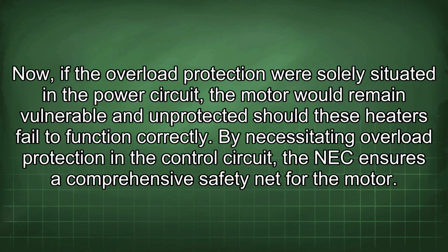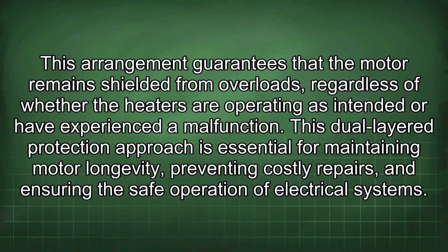Now, if the overload protection were solely situated in the power circuit, the motor would remain vulnerable and unprotected should these heaters fail to function correctly. By necessitating overload protection in the control circuit, the NEC ensures a comprehensive safety net for the motor. This arrangement guarantees that the motor remains shielded from overloads, regardless of whether the heaters are operating as intended or have experienced a malfunction. This dual-layer protection approach is essential for maintaining motor longevity, preventing costly repairs, and ensuring the safe operation of electrical systems.